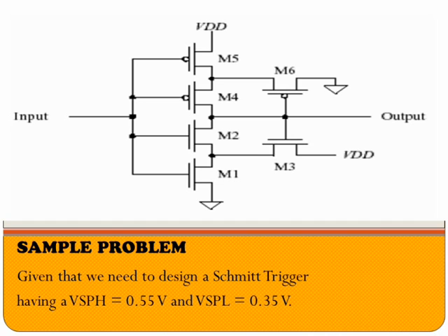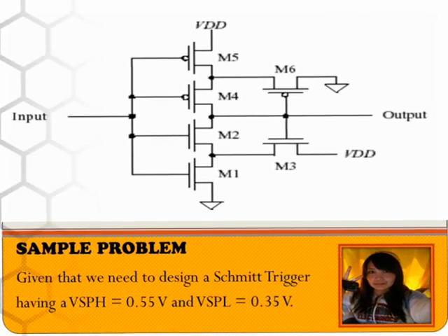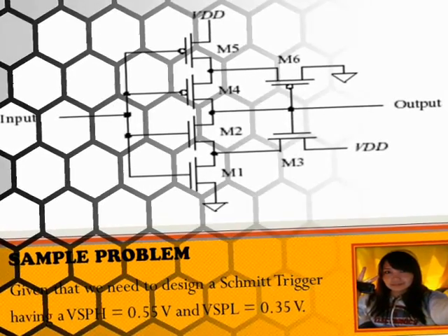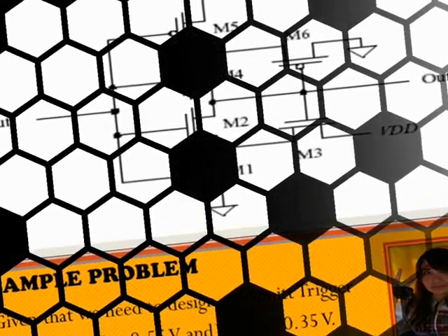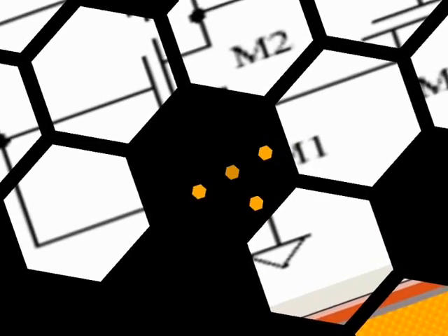The threshold voltage of M1 given by VTHN in this equation is the zero body bias threshold voltage, equal to 0.8 volts in our long channel CMOS process and 0.25 in the short channel process. Given a specific upper switching point voltage, the ratio of the MOSFET transconductances is determined by solving this equation.